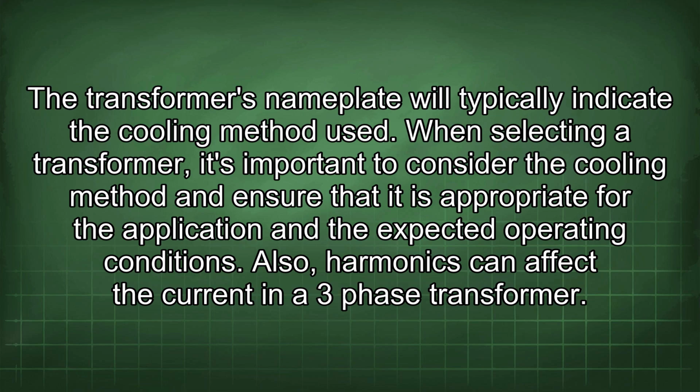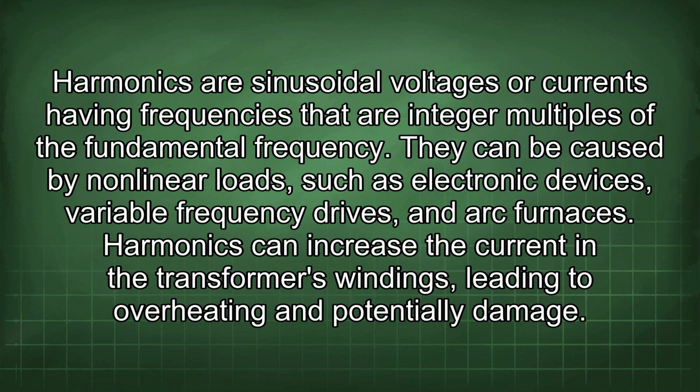Also, harmonics can affect the current in a three-phase transformer. Harmonics are sinusoidal voltages or currents having frequencies that are integer multiples of the fundamental frequency. They can be caused by nonlinear loads such as electronic devices, variable frequency drives, and arc furnaces. Harmonics can increase the current in the transformer's windings, leading to overheating and potentially damage.